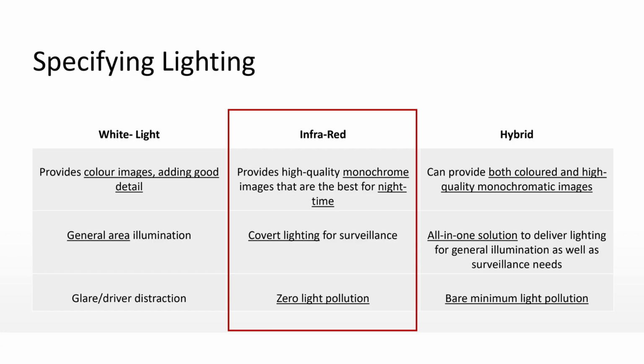However, as mentioned, because it is such a big bright red light, it needs to be used intelligently. So again, whether that be used off axis in a fast moving type application, or if it's for a barrier type application, I think that is more conducive to using 730 nanometers, as vehicles will be coming to a stop anyway. We've recently been invited to work on a number of toll station barrier type applications where they need to see inside of vehicles, and 730 nanometers is deemed to be acceptable, as mentioned, because the cars will actually be coming to a stop.